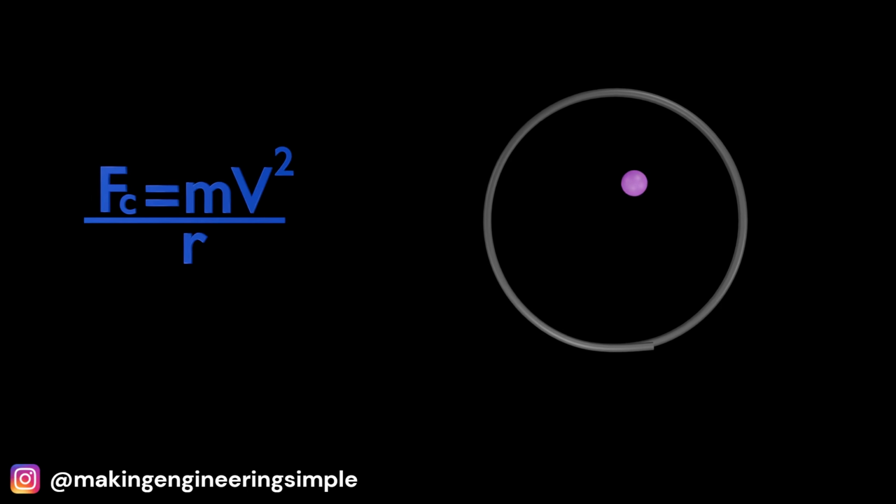If you decrease the radius, the force spikes. This is more effective for small particles. When we tighten the radius and increase the force, these tiny particles are finally flung to the edge and removed. It's a game of physics where every millimeter of the cyclone's diameter counts.